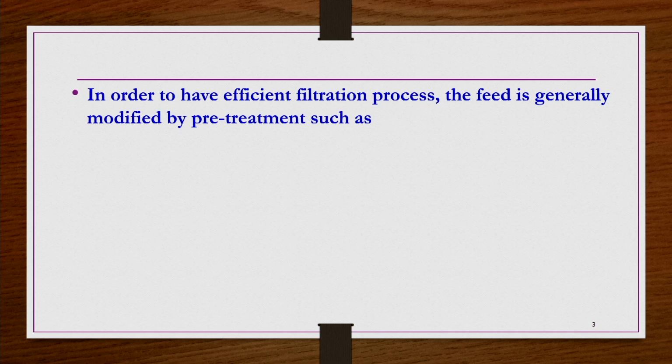In such cases, in general, some kind of pre-treatment is carried out. Pre-treatment, something like heating or recrystallizing of the slurry before separation, because sometimes if you have very fine particles in the slurry, they may clog the filter medium pores, and then gradually form an impervious cake on the filter medium because of these fine particles, and then further filtration may not take place.